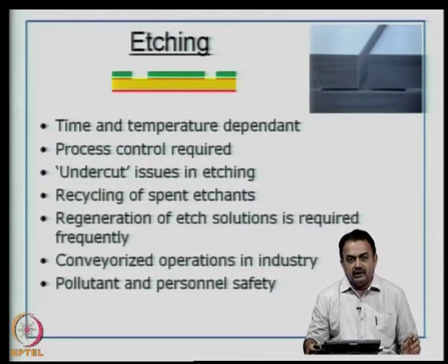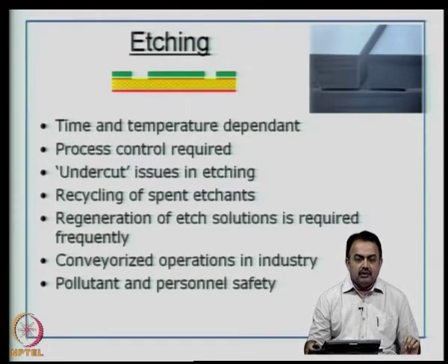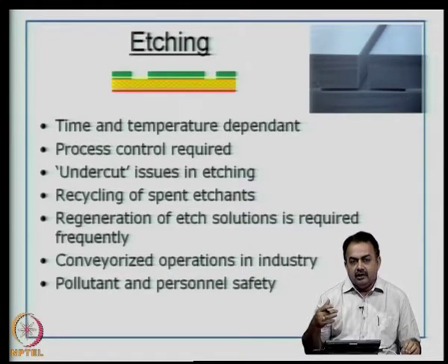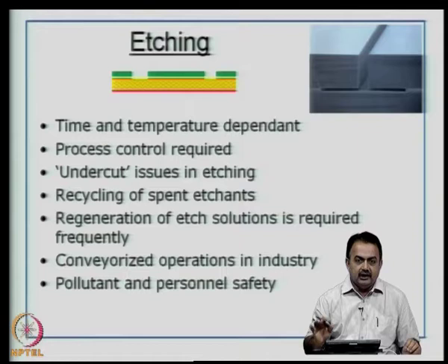If you take an etchant, let us say cupric chloride, you have to maintain suitable working temperatures for this cupric chloride. Then, if you are using machine based conveyorized etching, there are other factors that come into the picture that are based on the equipment, the machine. Therefore, those controls have to be taken care of.